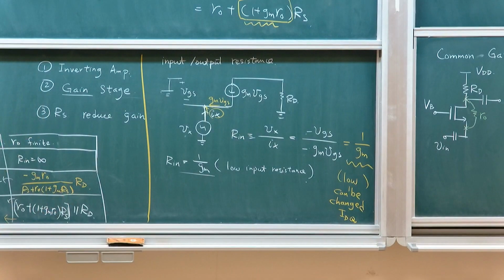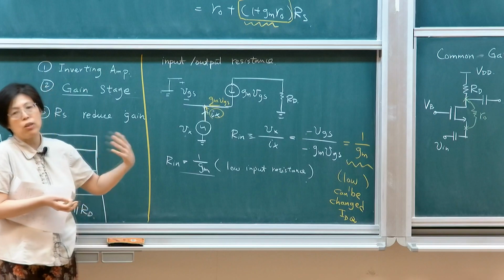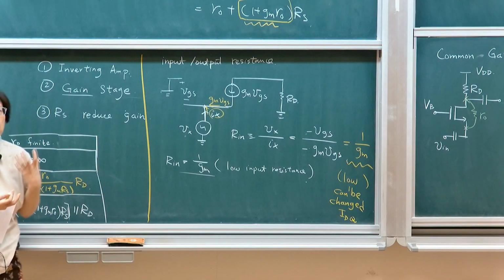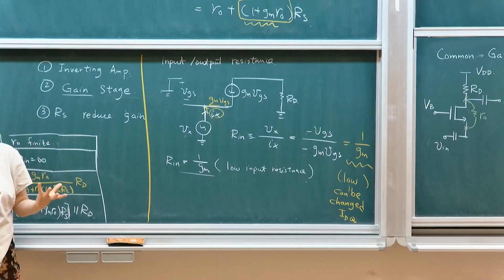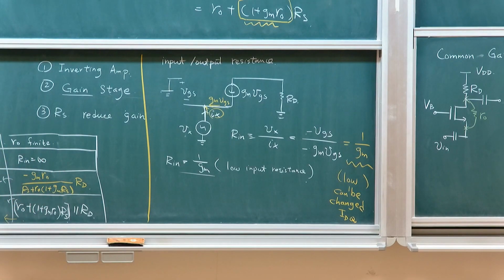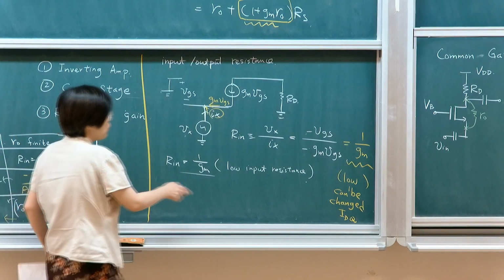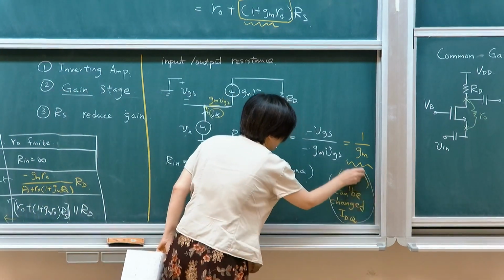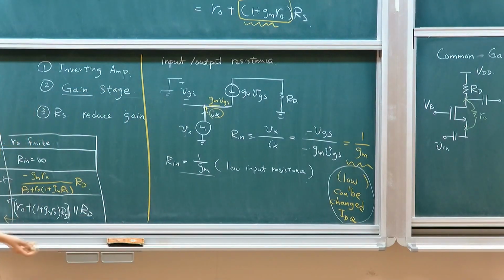This makes it less favored as a voltage amplifier if you have a source resistance. We're going to talk about that a little bit. It would attenuate because it requires a large amount of current. Therefore, it's not a good voltage amplifier because it would internally drop some signal. But it allows us to do impedance matching, that sort of thing, or to take in current signals.